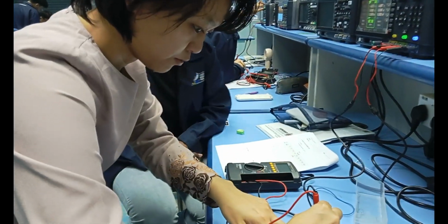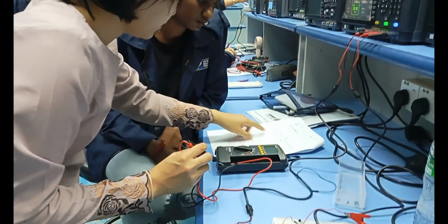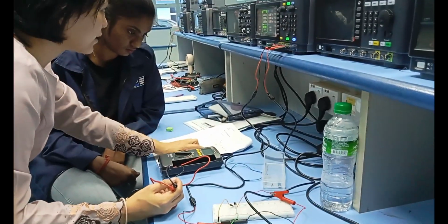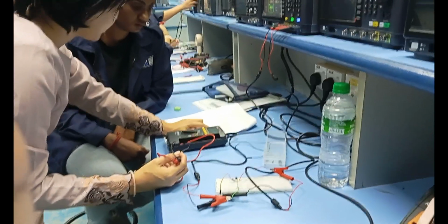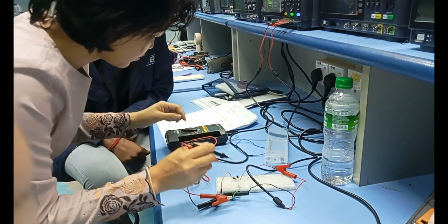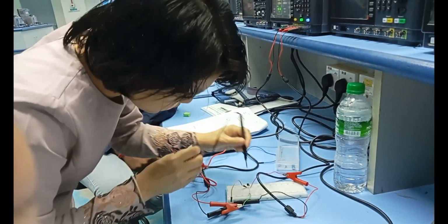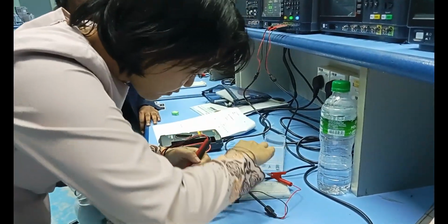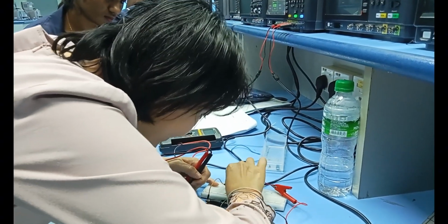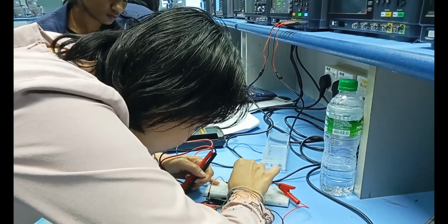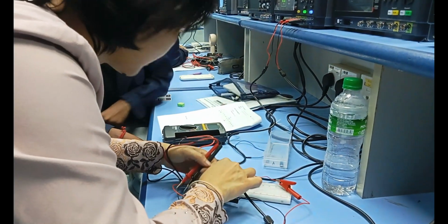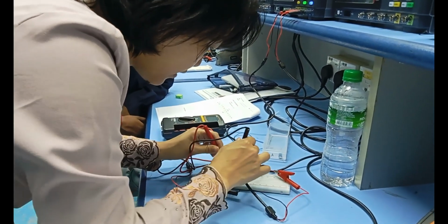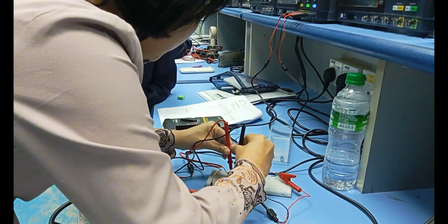Okay, now you take out. Now you want to find here this one for your V1. So your VCE, okay, you put 6 lah. You want to measure this value, right? Okay, 6. So you have to put this one to your VCE. C is above here. E is below. Okay, now this circle you have to put this current to this leg. To this leg. Okay. This one you have to put correctly because this one you didn't put correctly. So after that, you measure VCE.